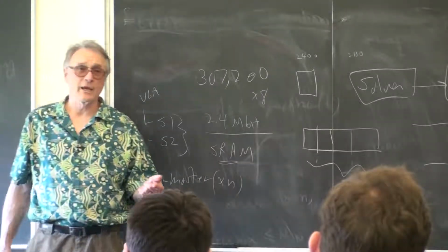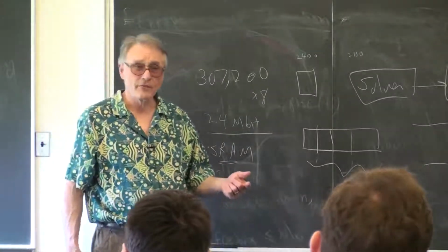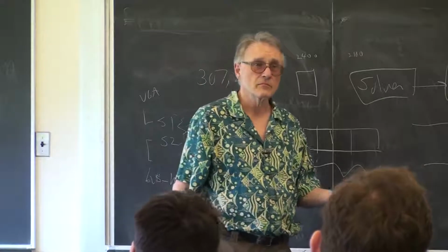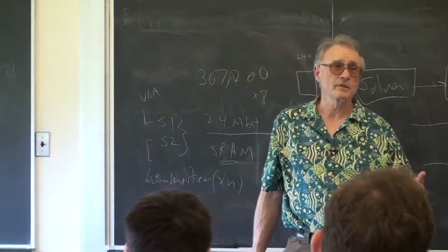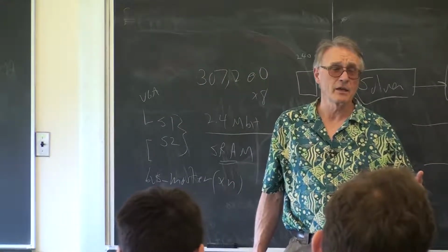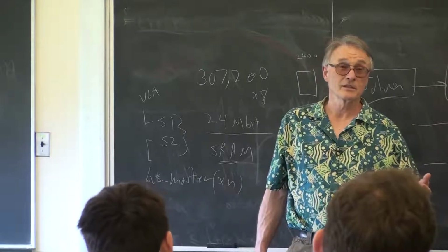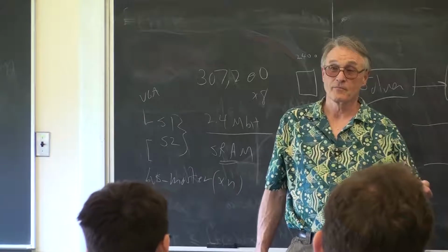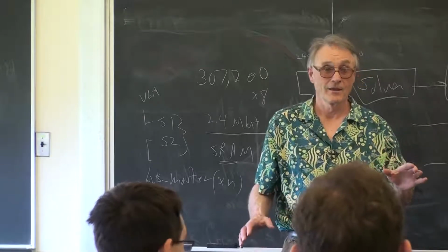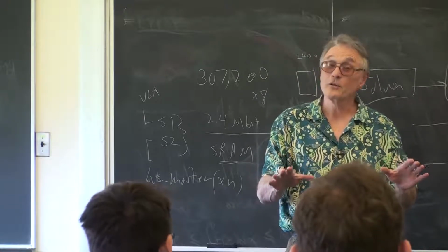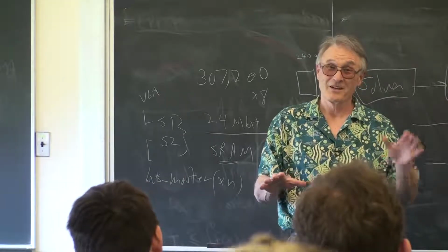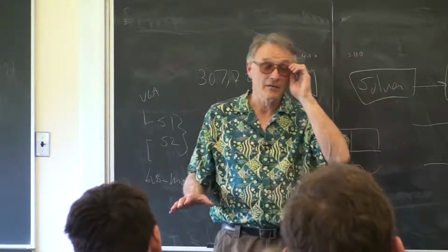I've written at least one AM transmitter, one FM transmitter. The AM transmitter broadcasts on the AM band at 1 megahertz. That's easy. You can do that by direct digital synthesis on the FPGA. It is illegal to broadcast on the... So you got to be a little careful.